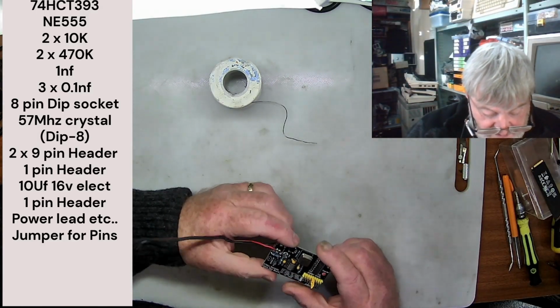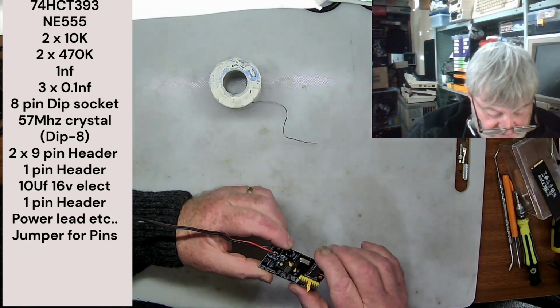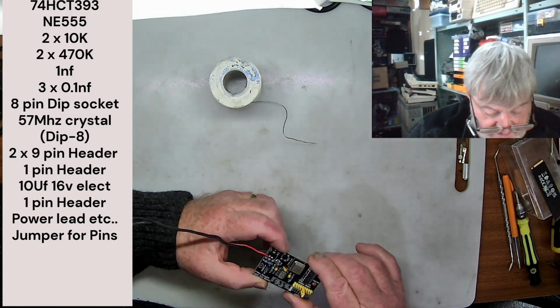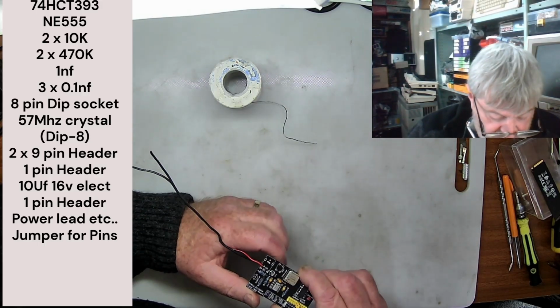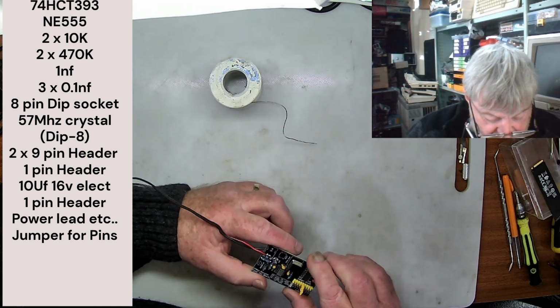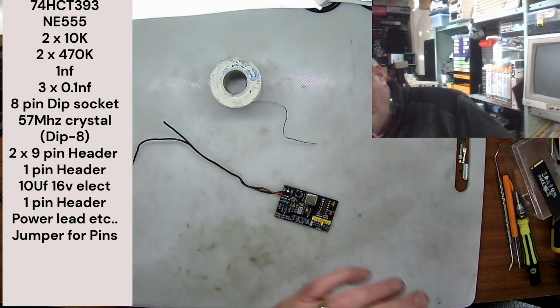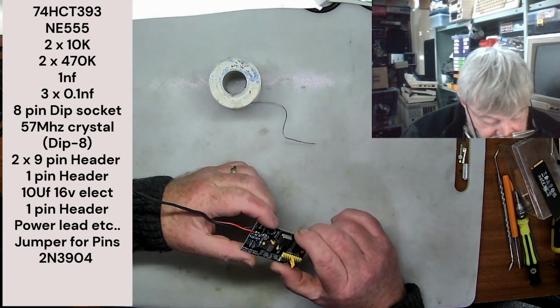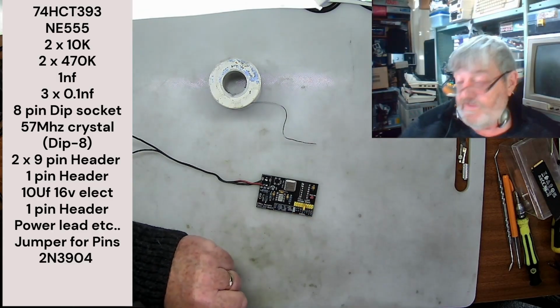Cool, so that's all done. The other couple of little components, I can probably dig out the transistor, and the reset switch, as I said, is the only thing that I'm missing at this stage. But it's not something I need to worry about. I mean, that part of the circuit will be just running anyway. So I'll dig out that 3904 and drop that into there.